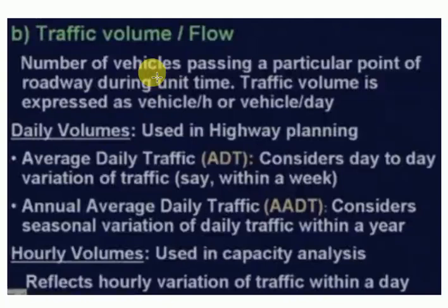So it is basically defined as the number of vehicles that pass a point on a highway or a given lane during a specific time interval. Suppose you have done the counting in 15 minutes. So you have to simply convert it into 1 hour. So basically its measurement comes as the number of vehicles per hour.